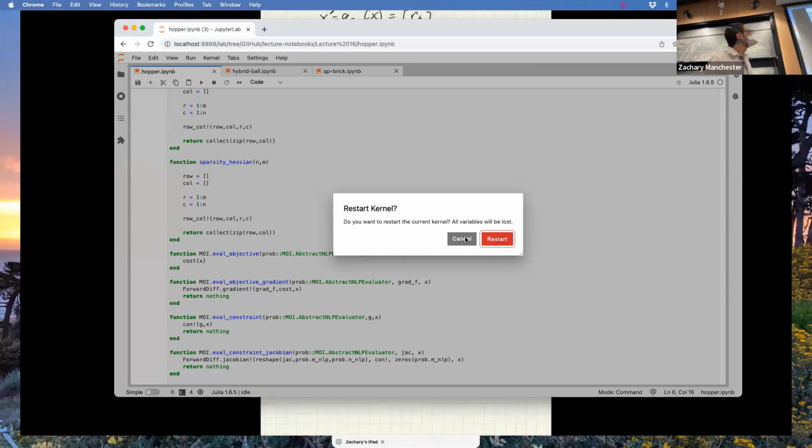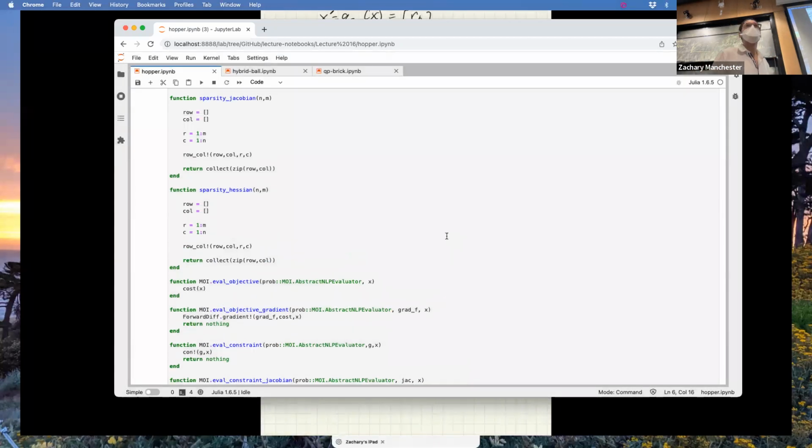Say this is like a Boston Dynamics Spot, and you're doing just locomotion. But if you wanted to use something like this, it's similar to the question of how do you handle all the different modes of slip that you can have? Yeah, so you kind of don't at this level. Remember, this is basically planning. This is offline generating a template motion. Online, you have some kind of feedback controller that's trying to track this on the real robot. And that's generally treated as a separate thing.